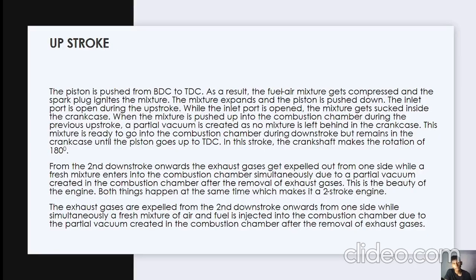Upstroke. The piston is pushed from bottom dead center to top dead center. As a result, the fuel-air mixture gets compressed and the spark plug ignites the mixture. The mixture expands and the piston is pushed down. The inlet port is opened during the upstroke. While the inlet port is open, the mixture gets drawn into the crankcase.